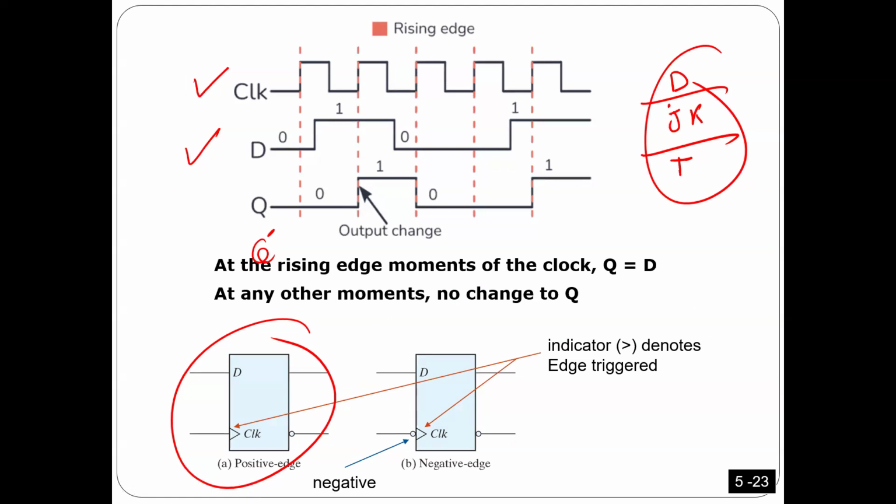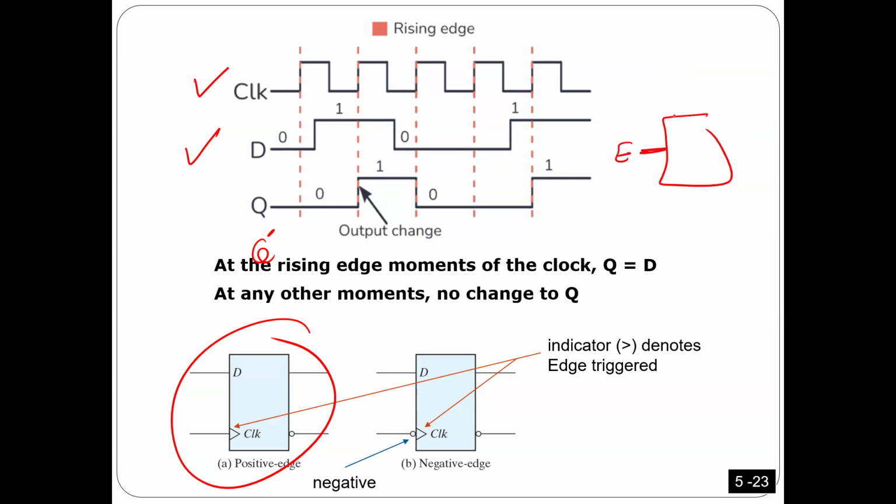Okay. For D flip-flop, this is the easiest one. All of them should have clock for sure, because any flip-flop should have clock. They can also, all of them can come with enable, come with clear, come with preset. This is optional. It may come with them or not.